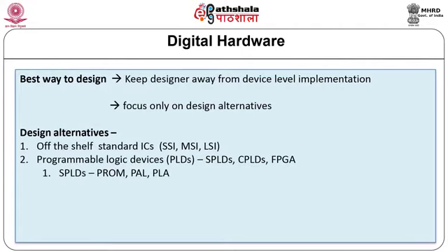There are three possible devices under SPLDs. It includes first, programmable read-only memory, that is PROM, in which the OR plane can be programmed. Second, the programmable array logic, PAL, in which the AND plane can be programmed. Third, the programmable logic array, PLA, in which both the AND and OR planes can be programmed. Effectively, if you look at it, either the AND or OR plane or both can be programmed, keeping one of them